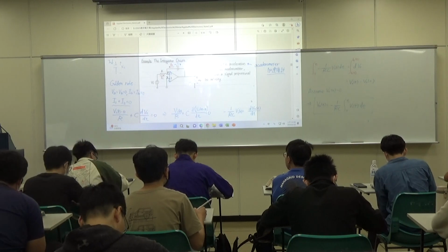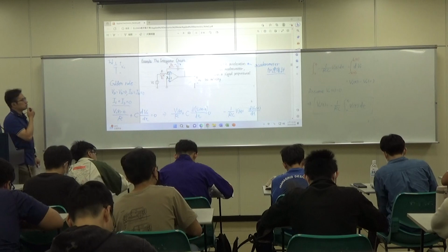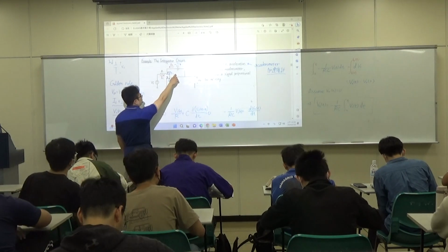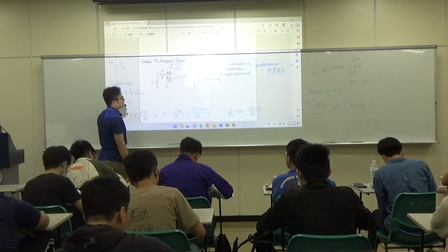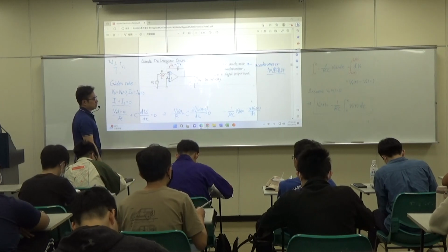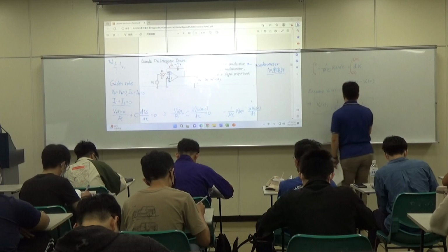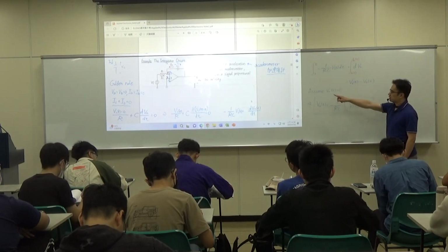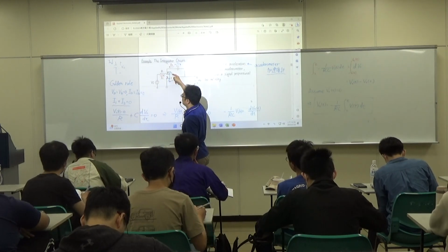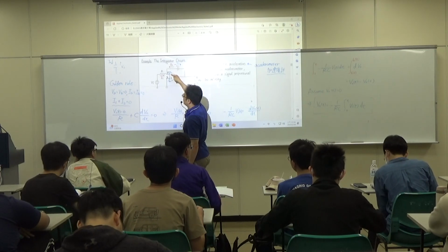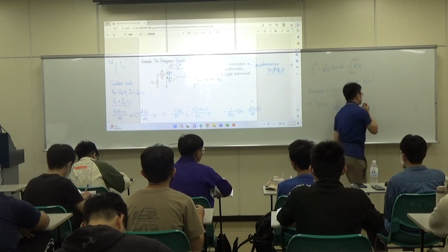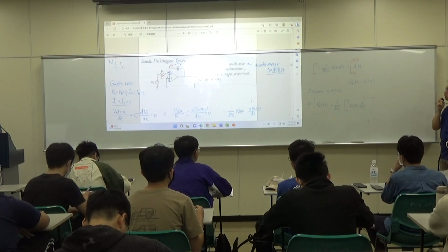What you need to memorize is if you replace the feedback resistance with a capacitor, it will become an integrator. It will integrate the input voltage, and because this input voltage still connects to its inverting terminal, the negative terminal, it has a negative sign. It's still inverting. So this is what you need to know.